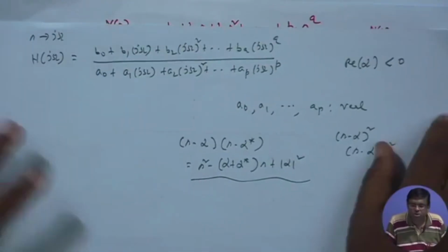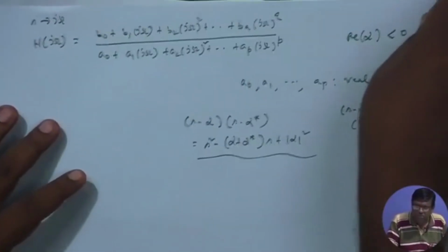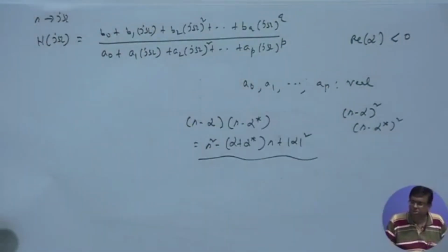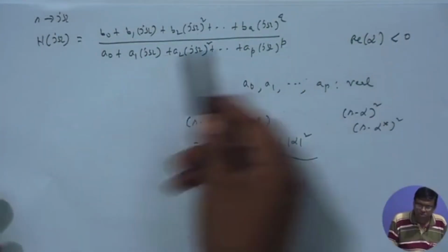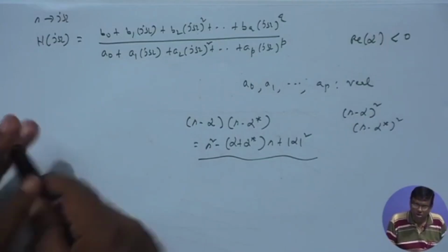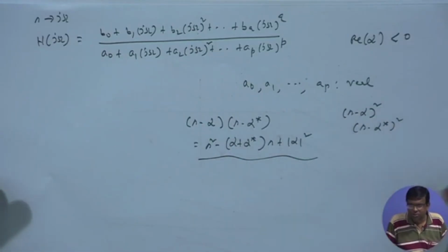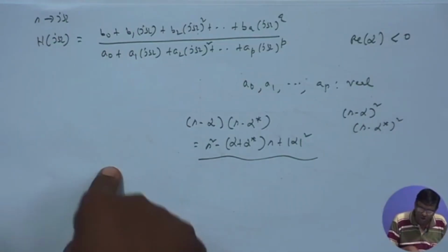With this, we will consider analog filter design, in particular Butterworth low pass filter design, how to derive that expression, all those things. And then we will try to move to digital filter design. We will show that a similar treatment cannot be carried out there because of some problem. And then we will show how to design these IIR filters, digital filters, by taking recourse to analog filters first.